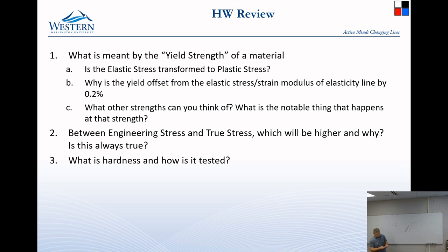So true stress, true strain will mostly always be above the engineering stress and strain. It is a little bit odd because the strain is measured differently. It's not quite the same number for strain, but the curve will still be higher for tensile loading. Some folks noted, well, maybe this is backwards in compressive loading. And the thing is, we just don't worry about it in compressive loading, because in compressive loading, it doesn't neck down. And stuff, once you get to plastic compressive loading, just goes totally berserk. And so it fails in odd ways.